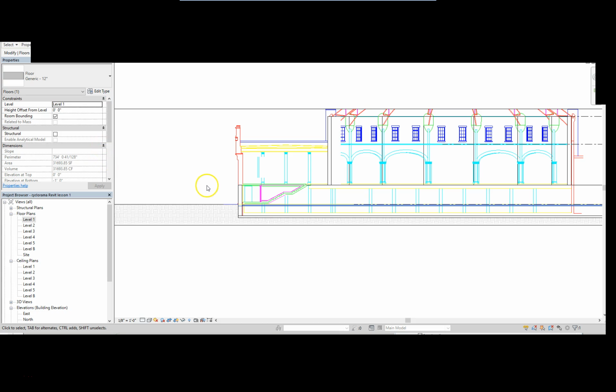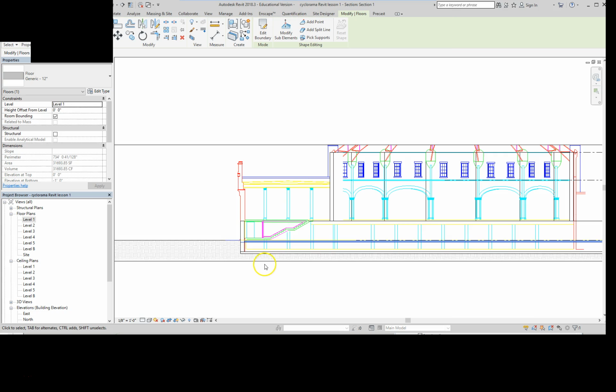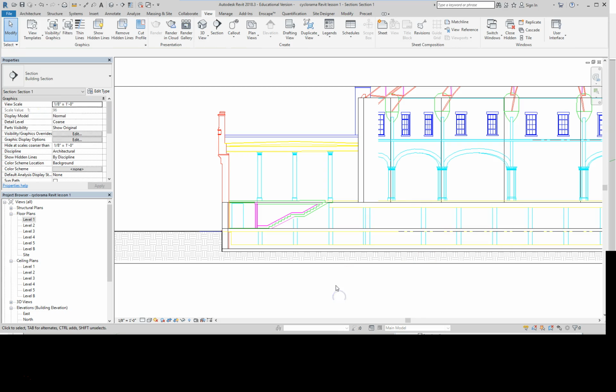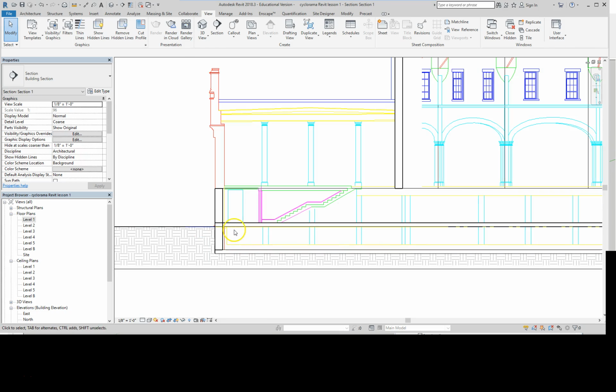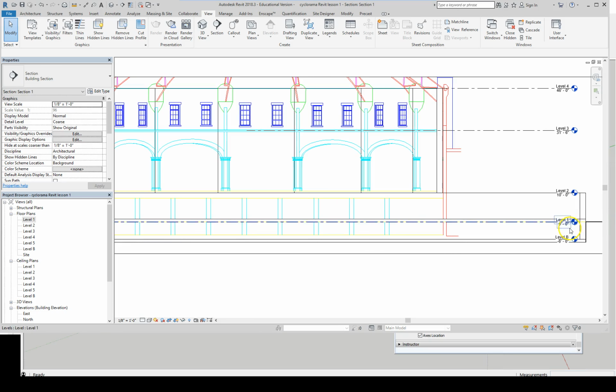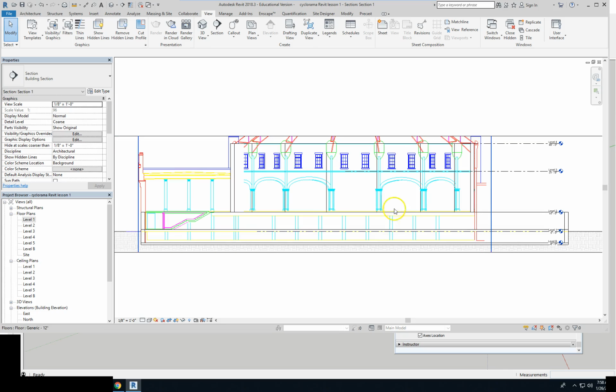We'll have to wait for VDI to redraw. We'll give it a height offset of 1. Alright. So you step into the building, we need a couple of risers to get into the building. Level 1 is actually the level of the finished grade. And slightly above level 1 is that inside floor.